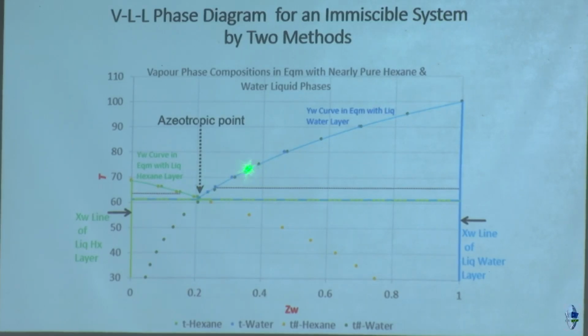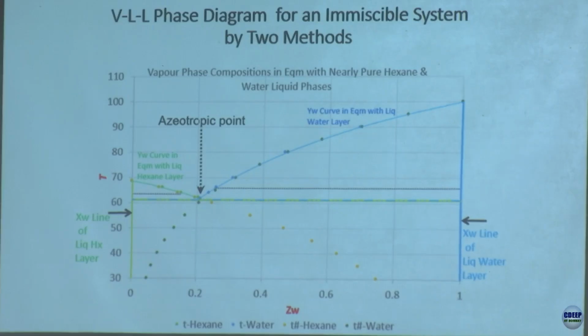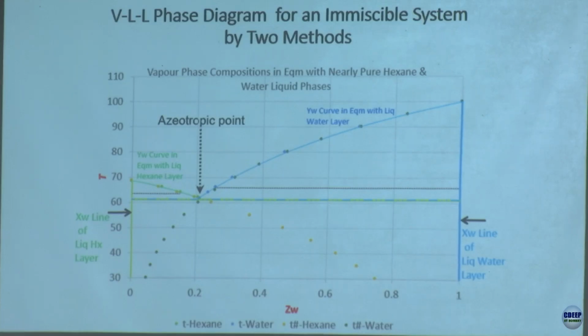And in fact, what it means is that the latent heat of vaporization and the boiling point, these two data points were able to predict in an indirect manner the vapor pressure which we used for the earlier exercise. So that is a method for even predicting the vapor pressures which Rochesh was mentioning.